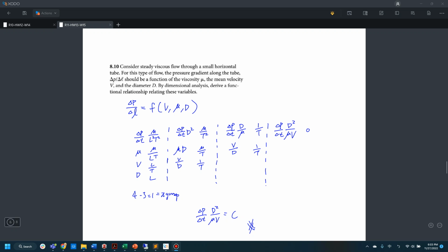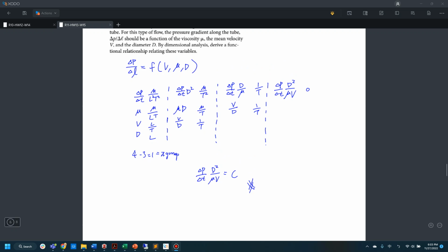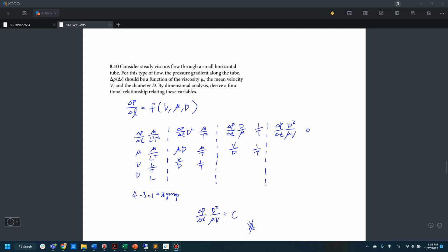So you just divide the first term by the second term, then you get the dimensionless variable shown in the last column. And that is our pi group written down here. So follow the same steps, and you should be able to find a pi group for all equations.